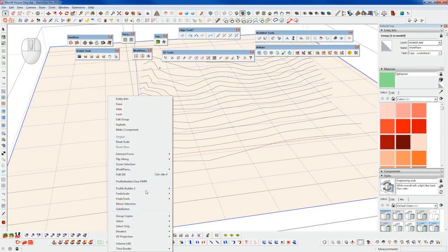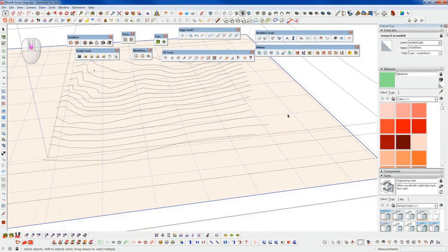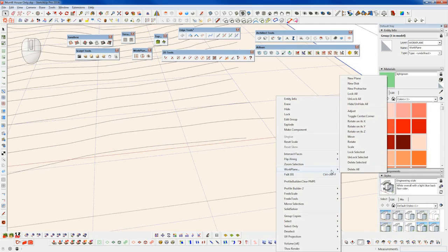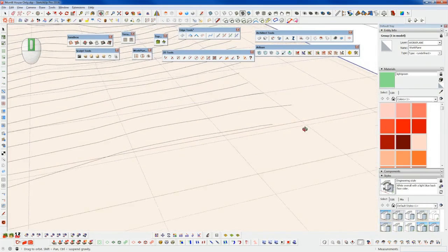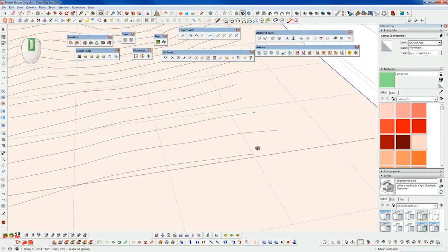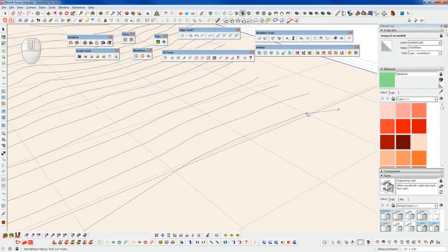So that's another option. And with the work plane, it usually works better to work from a lower elevation to a higher elevation, because it's hard to snap coming back down. So because we're restricted here, if I wanted to now grab this and try to snap it down here, it's a little more challenging sometimes to get it to do that.